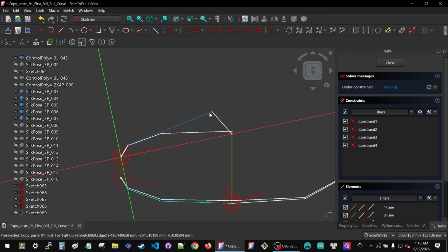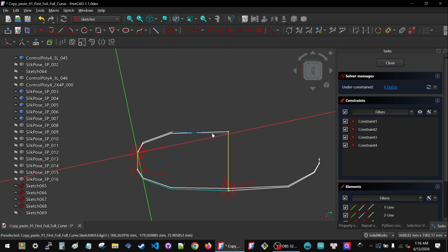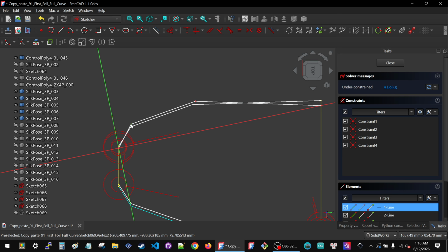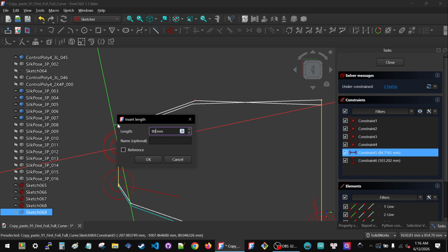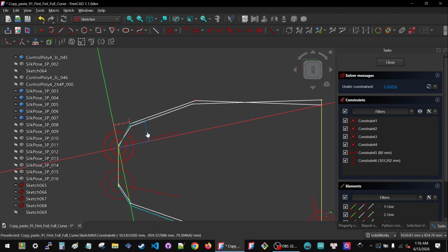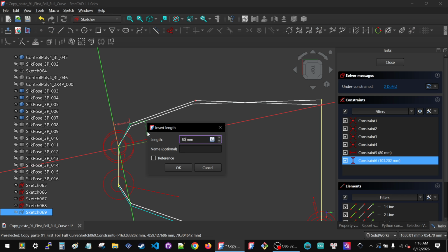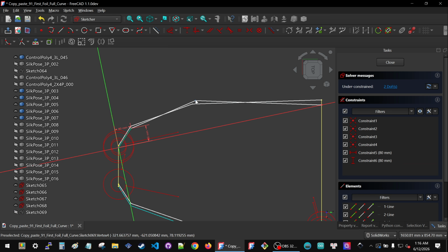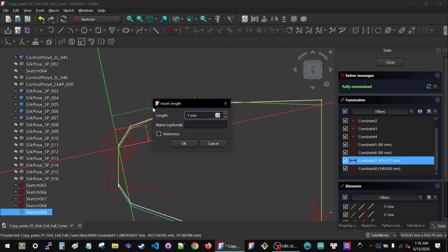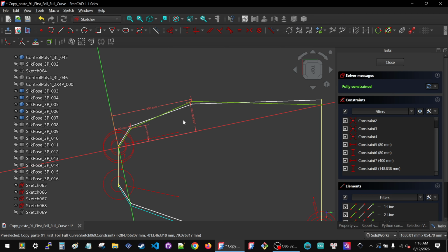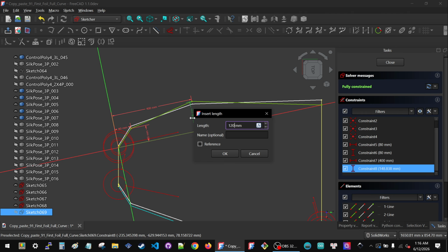I vaguely align this poly. See, why does it do that? It's because it's had the line selected. I just want the point. I don't want the line. Okay, but I get it close by hand, and now that I'm close by hand, when I do KL for constraint lock, the numbers are almost exactly what I want. And since I always change things to simple round numbers, it's easy for me to actually assign the correct numbers. It says 418. It's 400. It says 148. No, it's 120.